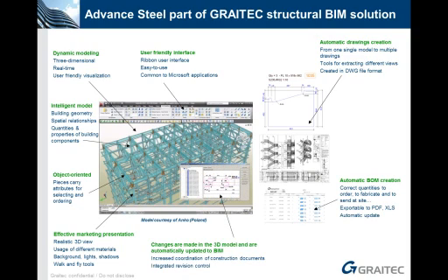And what is important, in case of modification, we have the document manager, which helps the user to see which document needs an update, and the update is done automatically with revision control, revision clouds, which are created automatically on drawings. Advanced Steel can be used in a single user mode or in a multi-user mode if you have different users who need to work at the same time on the same file of the same model.